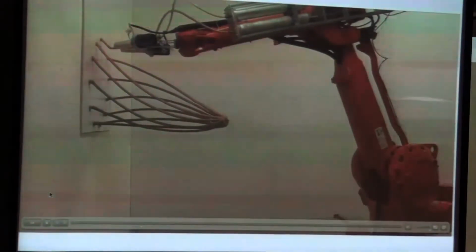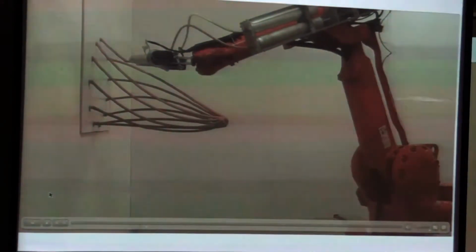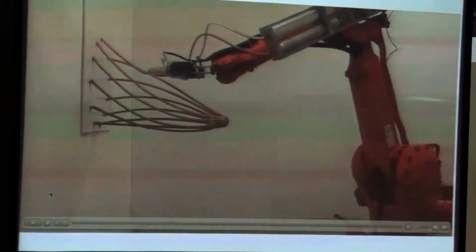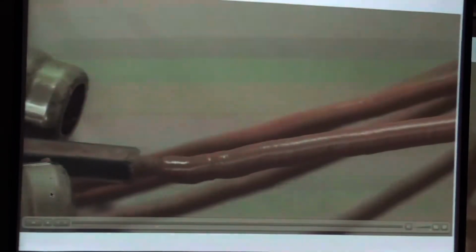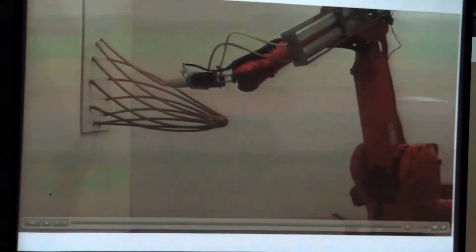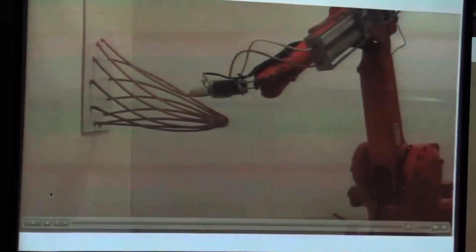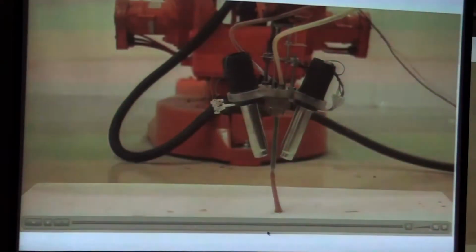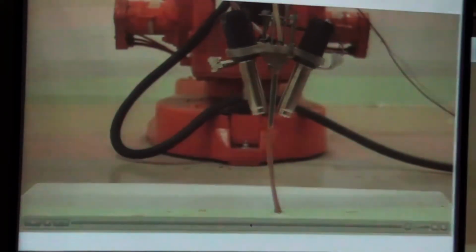attached to the robot. These are nozzles that, on the one hand, give out material, and on the other hand, they dry and cure the material that is getting out of the nozzle. So the parameters of how much material is going out of the nozzle, what is the mixture between the 2 polymers, and the speed of the robot movement can allow us to control what kind of structures we can arrange so that when the material goes out of the nozzle, it's being solidified and allows us to create this kind of free-form anti-gravity object modeling.